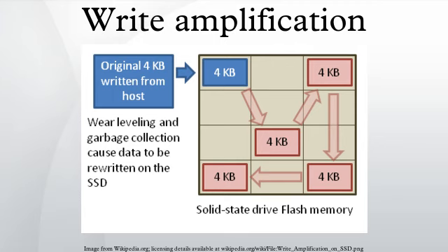Product statements. In September 2008, Intel announced the X25-M SATA SSD with a reported WA as low as 1.1. In April 2009, SandForce announced the SF-1000 SSD processor family with a reported WA of 0.5, which appears to come from some form of data compression. Before this announcement, a write amplification of 1.0 was considered the lowest that could be attained with an SSD. Currently, only SandForce employs compression in its SSD controller.